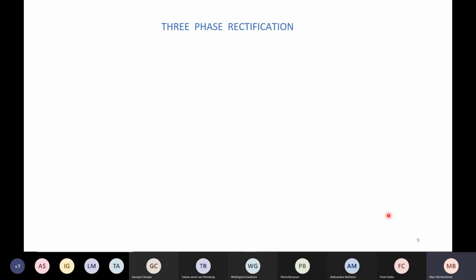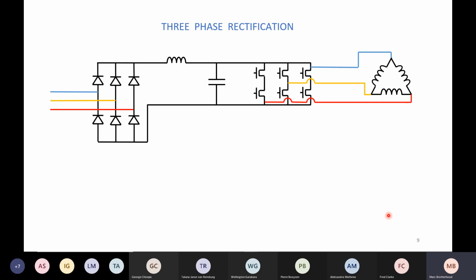So now this is where we separate the men from the boys, when we start going to three-phase rectification. Nearly all the big sites you will work on will be non-residential, and they will run primarily in South Africa on 400 volts. A lot of our supply is 400. Certain countries like the UK might get 380 volts, and certain European countries 415 volts. Now this is a much more complicated looking circuit, and you'll notice we don't have 4 diodes, we've got 6.